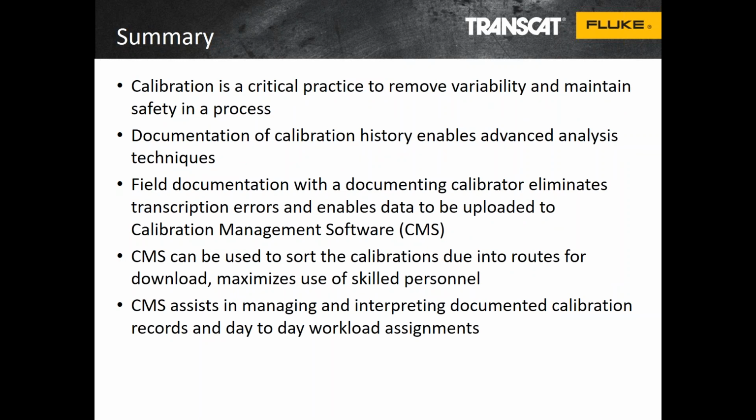So to summarize, calibration is a critical practice to remove variability and maintain safety in processes. Documentation of calibration history enables advanced analysis techniques. Field documentation with the documenting calibrator eliminates transcription errors and enables data to be uploaded to calibration management software.